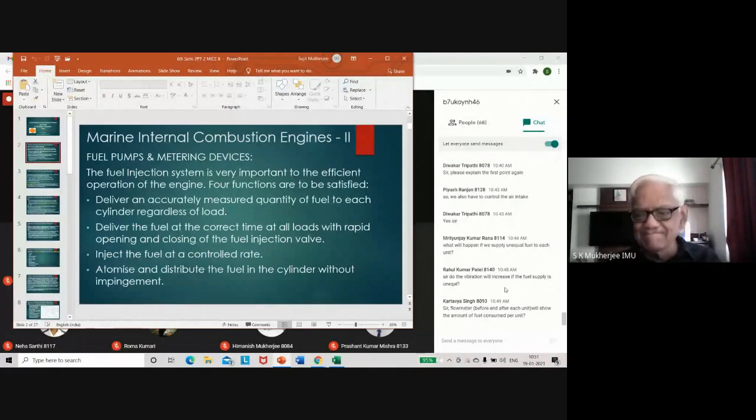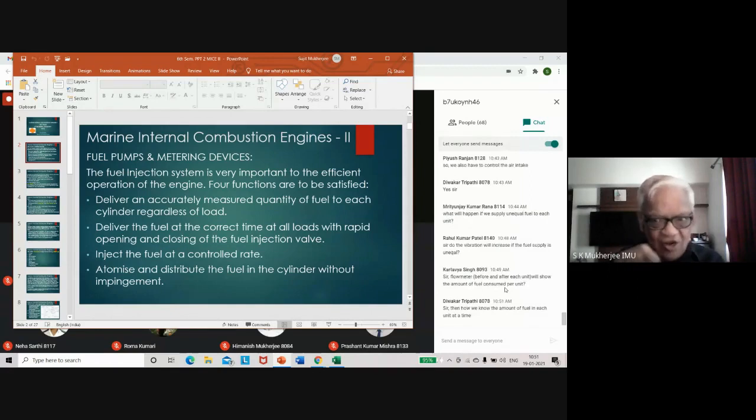No way. But the fuel pump itself, which controls the fuel quantity to the engine, works with the help of a fuel rack. This fuel rack has a scale on it. This scale has readings from 0 to 90. So your duty is to check whether that scale and the pointer are showing the same for all the fuel pumps.